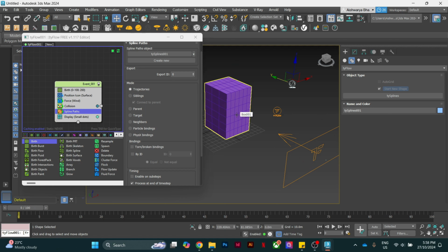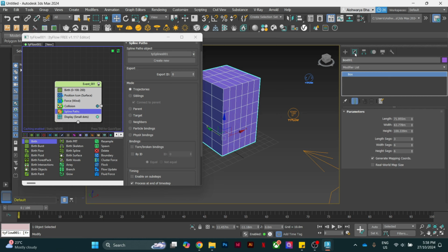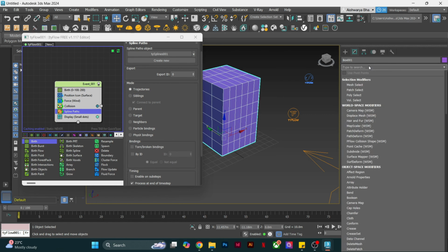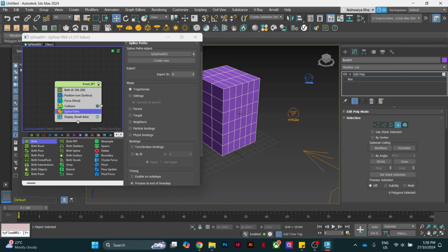Some things you can do as well, so you can create some holes within this building, just so we can see if some of the wind actually does go through the building from those holes. So what we'll do is go edit poly, we'll pick polygons, and let's do some random ones. So we'll do two of those, and shift.